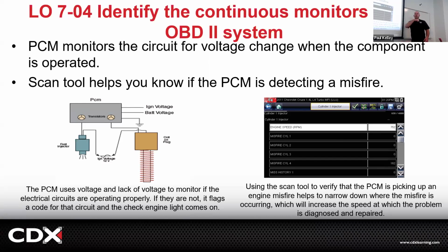And you'd be like, oh, it's got a misfire. Then you could do some of those tests from the first thing that we did, right? You could do the power balance. You could do some of the basic misfire testing. Then you might even do compression, be like, the compression's good. You could do spark and the spark is good. Then you go into fuel and be like, yeah, it's got a misfire, but it's got a problem with the injector. So it gives us a big jump because we got a code and it says injector circuit number 1.